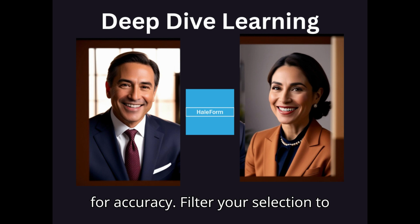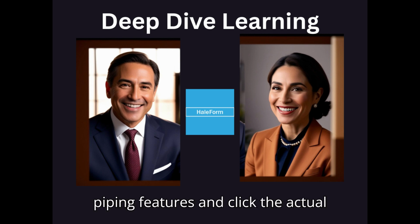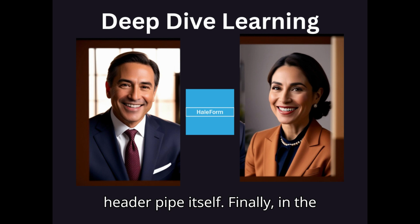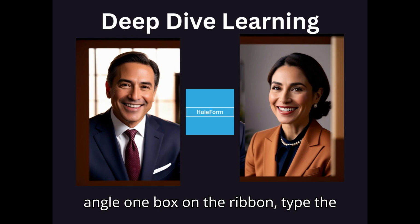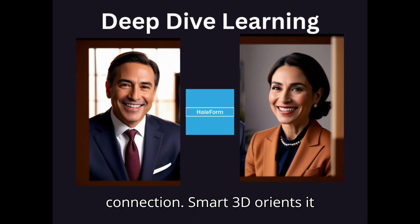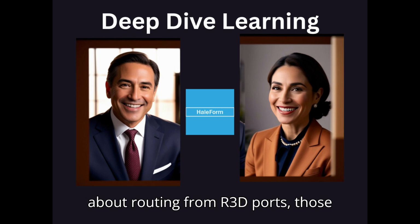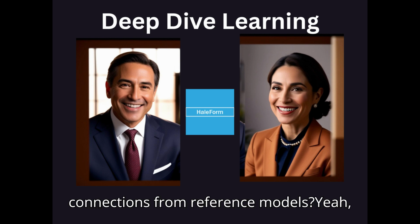Then this is important for accuracy. Filter your selection to piping features and click the actual header pipe itself. Finally, in the angle 1 box on the ribbon, type the exact angle you need for the branch connection. Smart 3D orients it precisely. Very controlled. Nice. What about routing from R3D ports, those connections from reference models?